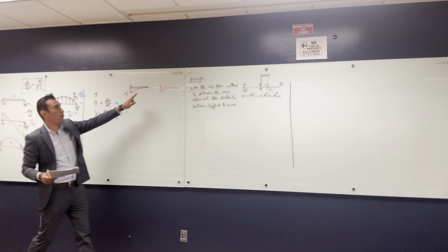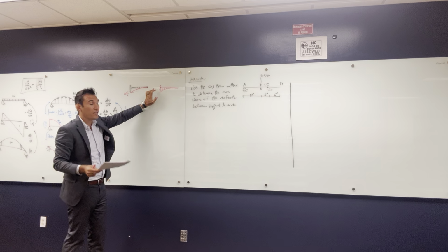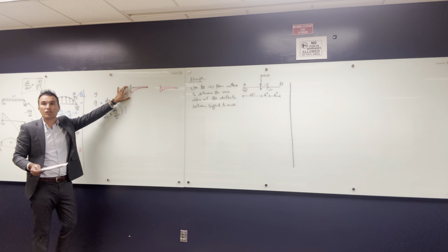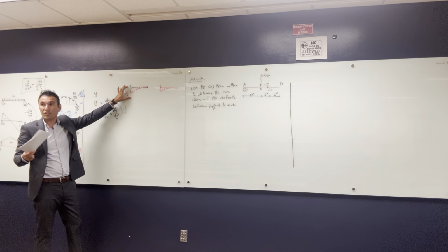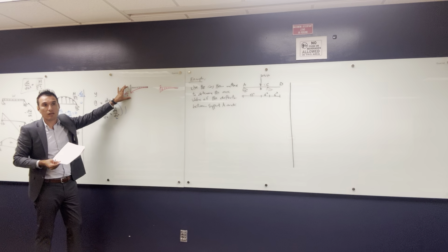So that means there is a theta and there is a deflection. However, the original beam has fixation here, and at the fixation the slope is 0 and the deflection is 0. So this doesn't make sense, right, if I use the conjugate beam.